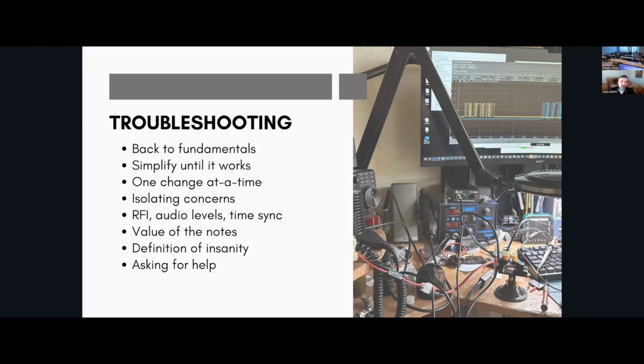So before any troubleshooting on the digital mode starts, make sure you can make a regular voice QSO at the power you're trying to achieve and at the distance that you're trying to operate, because digital modes will pull out weak signal, but if there is no signal or the radio is not working right, connecting a computer will not fix that.